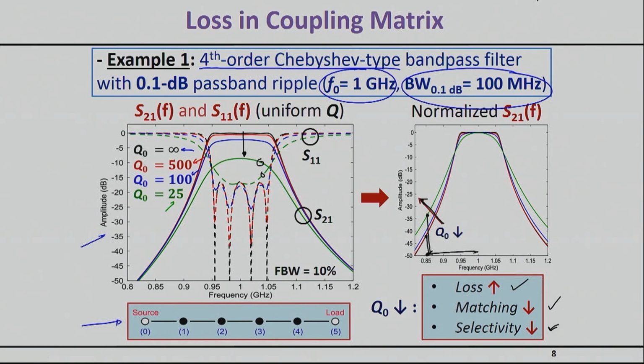And so because of that Q, you may have to, unfortunately, increase the order of the filter. So maybe because you don't meet the spec, you might have to go from fourth order to maybe sixth order. But guess what? Sixth order will actually push and punish the insertion loss even further. So basically, you can't win unless you invest in a better resonator.